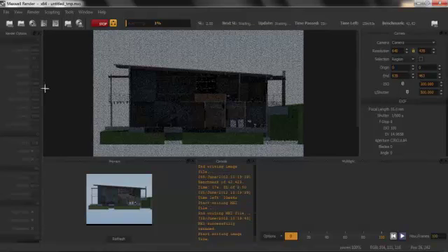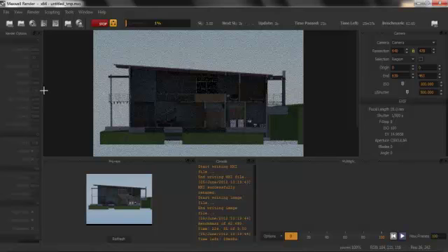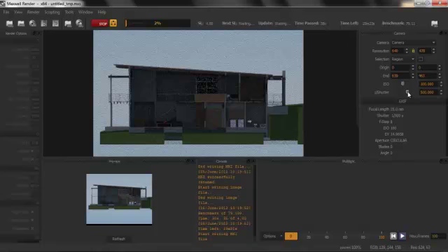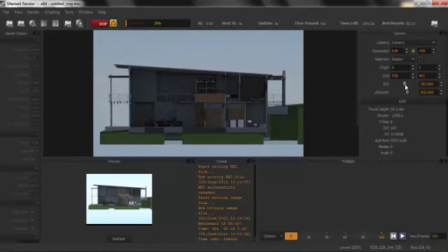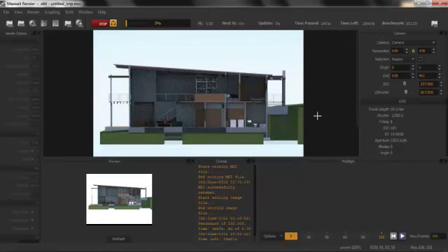Adjusting the layout in Maxwell Render is as simple as adjusting the layout in Maxwell Studio. What I have just done was moving my camera panel to the side of the image so that we can talk a little bit about how much we can adjust in Maxwell Render. Since multi-light was disabled, I will now be able to adjust my ISO and my shutter speed directly while my rendering is going. If we look at the preview while I adjust it, you can see instantly what the result would be with different settings. And then my rendering gets updated automatically as well.